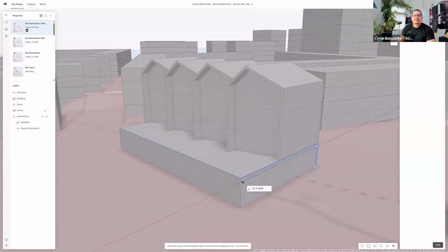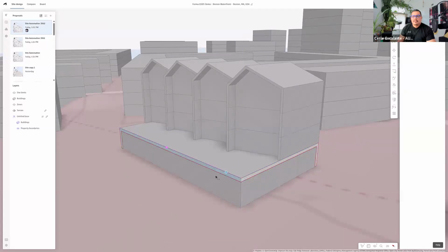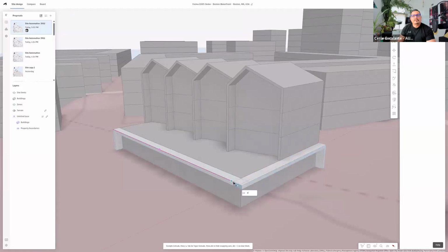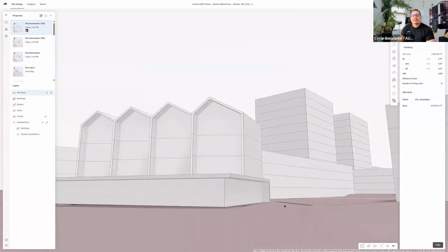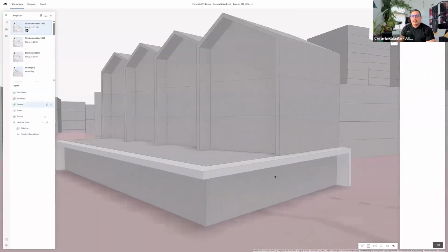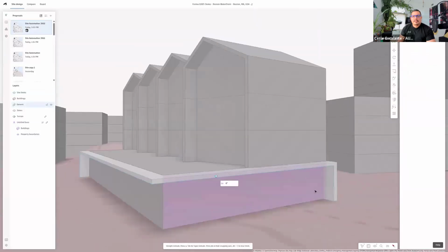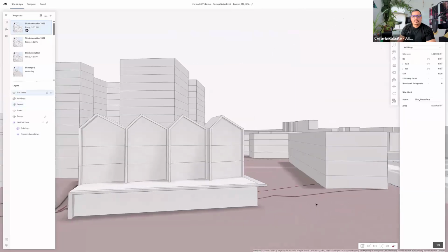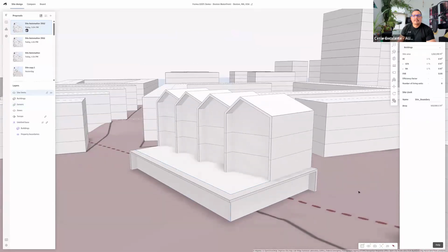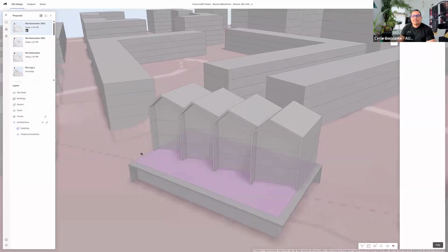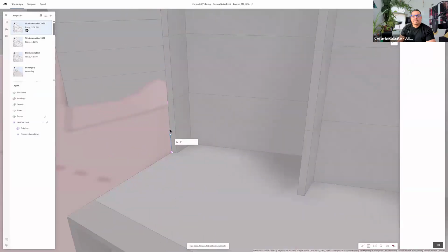You can represent handrails using sweep profiles along a path. The 3D Sketch functionality is very intuitive. It relies a lot on built-in snaps along existing lines and edges in the building, and a lot of the operations are just a matter of click and pick.